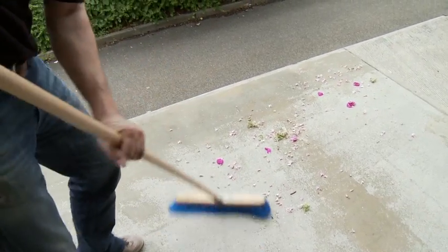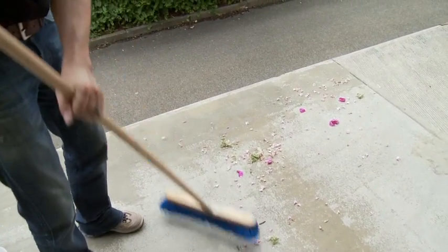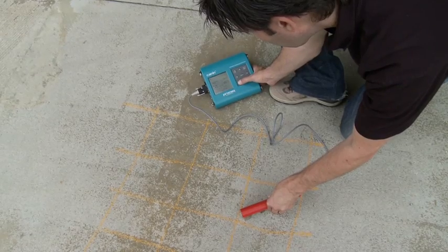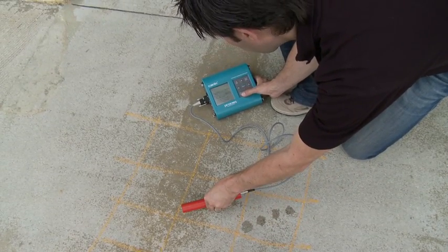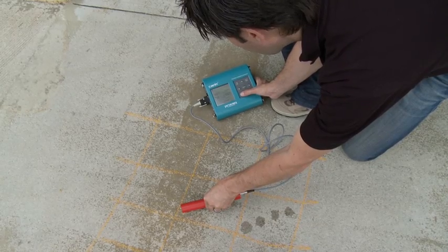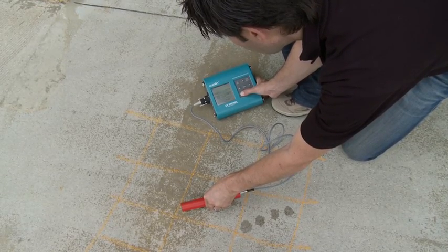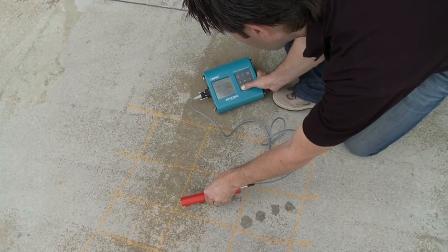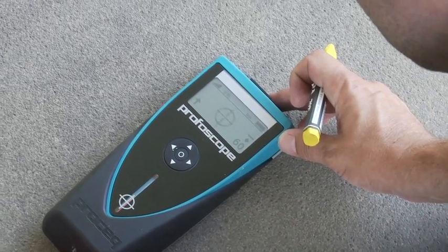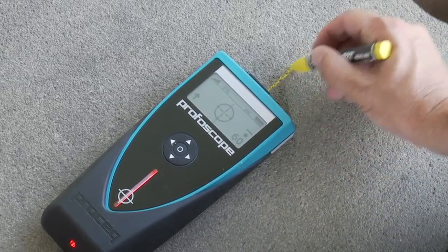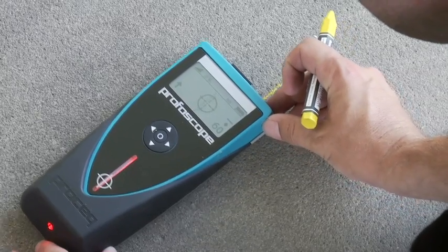When carrying out a measurement, make sure the surface area is clean. As far as possible, reinforcement bars should not be directly beneath the probe and should not run parallel to the probe. The recommended procedure is to measure diagonally to the rebars. In order to ensure this, it is recommended to map out the rebar grid using a profoscope.